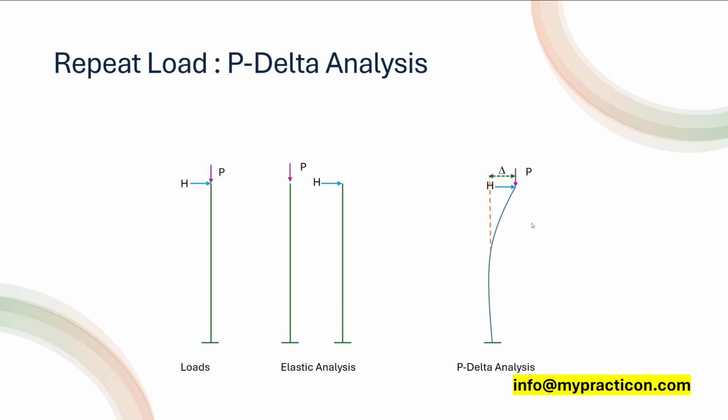But similarly, there are other conditions. If you have a truss system, multiple loads are applied. The bracing member sometimes may undergo compression only or tension only, and so it will be assigned that way. In these kinds of situations also, we had better go for the repeat load combinations. Overall, if we apply the repeat load, we are always safe in the analysis and design.